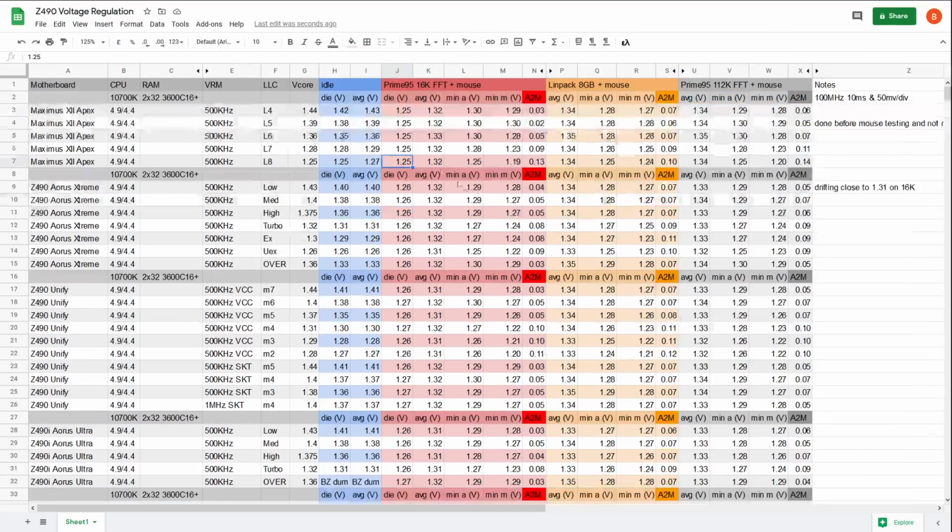Potentially even worse, because the reason this measurement is higher than the die-sense voltage is because the coax goes to the CPU substrate. It doesn't go directly behind the CPU die. So the measurement is a little bit high because there's still resistance in the substrate of the CPU itself. So that's further limitations of the test equipment. I don't really think there's a reasonable way to work around this limitation. There's just not really much I can do about that.